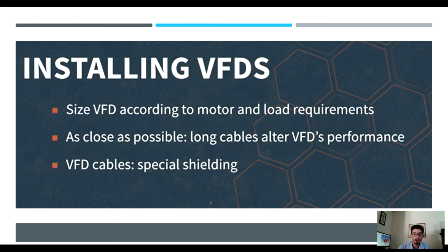So it's usually not the case, or if this is the case, it's very expensive, that it tells you press 1 for 420, press 2 for 450, press 3 for 200 RPMs. No, they're a continuous range of RPMs where you, in your code and your controller scheme, have to tune what particular RPM you want based on a set of voltage and frequencies that you obtain.